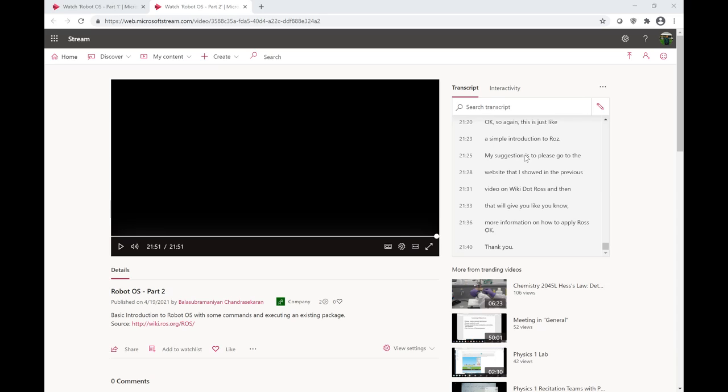With ROS, if you practice the tutorials from the website, I think that will give you a good understanding. But there is lots to learn in ROS. It's basically like writing your own application, developing your own robotic application. The first step is to start with ROS, and once you get familiarized with it, like writing your own publisher and subscriber, you can extend it and explore visualization tools like RViz, and then Gazebo, which is additional software.